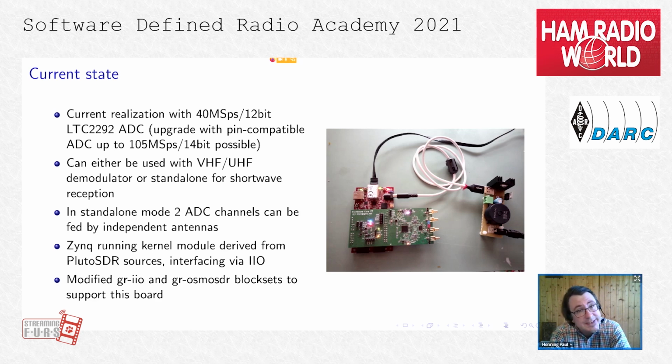Of course, the bottleneck in this is the gigabit Ethernet, because 1 gigabit is rather easily saturated, and you have to be aware that on the other side of the gigabit link, you have to process this data somehow. So it means real-time processing on the receiver side also needs to cope with the amount of data that's rushing through your gigabit Ethernet link.